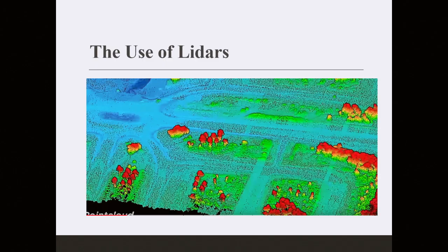Now somebody might say, okay, but a crack would do the same if you have a longitudinal crack. That's where the AI comes in, because you teach your machine that this pattern of capturing the drop on the asphalt is equivalent to a pothole. The other pattern could be a rut. A third pattern could be a crack. It's like image recognition.